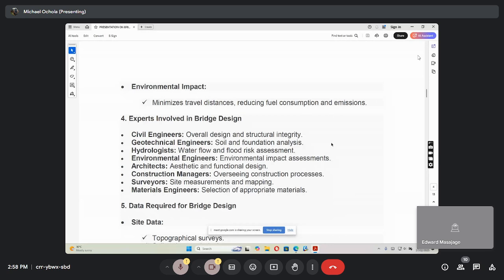If a bridge is situated in a place which is contaminated with chemicals, if you have a discharge from a chemical industry, the way you approach your bridge structure and cover, concrete cover and the rest, is different from when a bridge is somewhere in the remote area of Karamoja and Kisoro. You may find the soil properties, the pH is far below 6. Now, you call it in O level and A level, this pH value. You see, now you need them as a bridge engineer, because if the pH is less than 6, my brother, you have to be mindful of early corrosion.